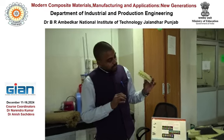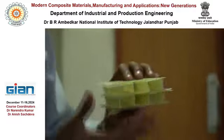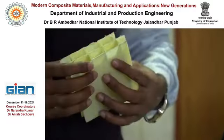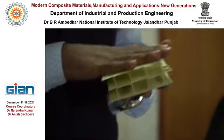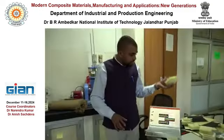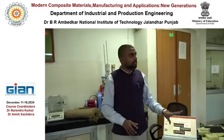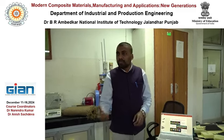And after making this corrugated structure, it is stacked together according to the desired thickness, how much thickness you need. Based on that, it is stacked together and simply stuck by resin. Again, this is one of the good sandwich composite materials, which can also bear a good amount of load.